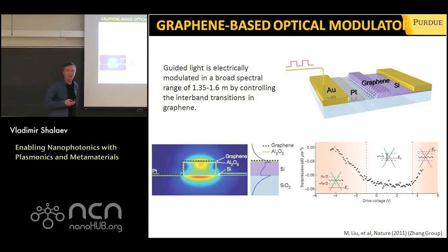So that's of course elegant because it combines graphene, a wonderful material, and you could control optical properties electrically. So that's an electrically controlled modulator. That's relatively old already; there are works on that. People suggested a different modulation. It's more efficient because you should remember that absorption of graphene is relatively small, around 2%.